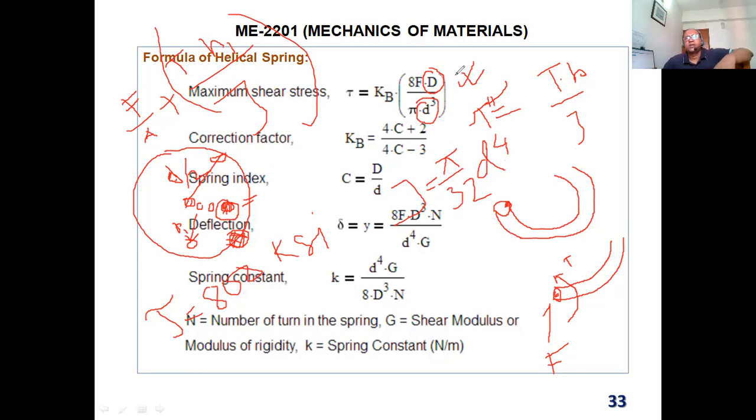That means the polar moment of inertia represents that if this value is high, then you need more torque, or it has more resistance against the torque. Say I'm giving you a pen with a small diameter, you can easily apply twisting.